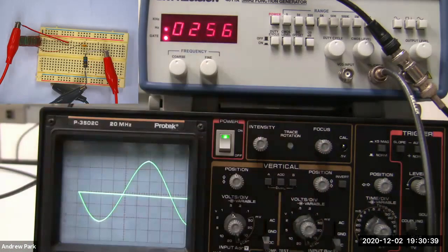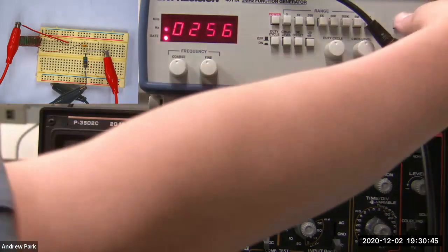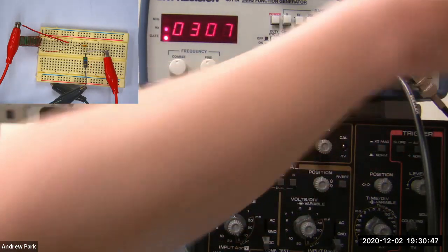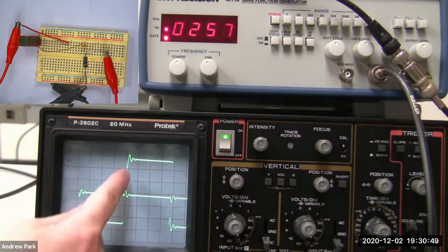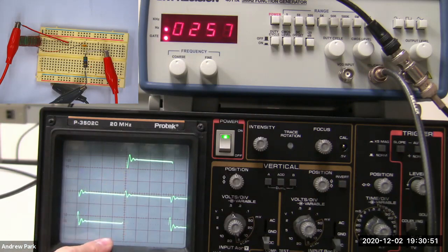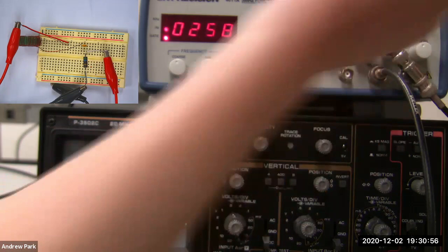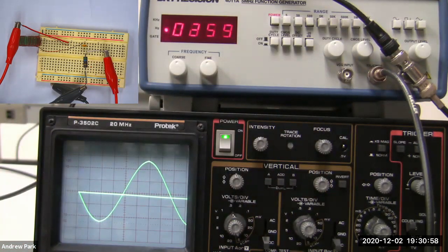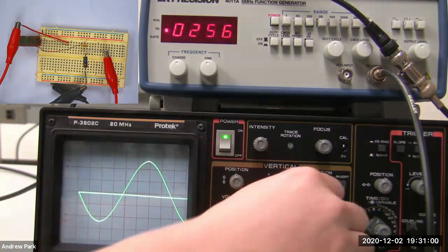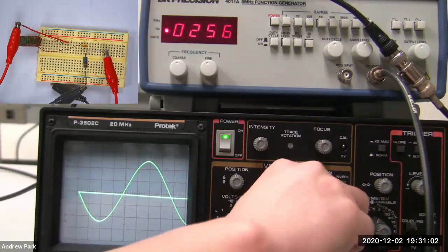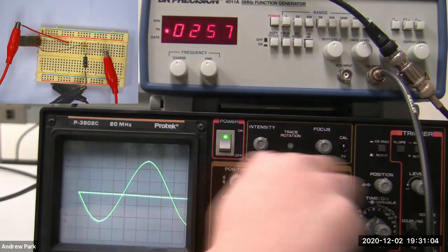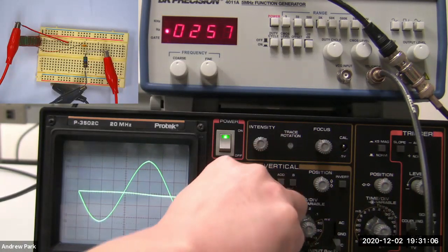With the sinusoidal signal, you see that the imperfections that I had before are gone, because this imperfection mostly has to do with the sudden change that I'm trying to drive. So when I'm not trying to do that anymore, and I'm driving with a gentle sinusoidal signal, it behaves much more ideally. And when you're working with the AC signal, you will almost always be using just the sinusoidal signal.